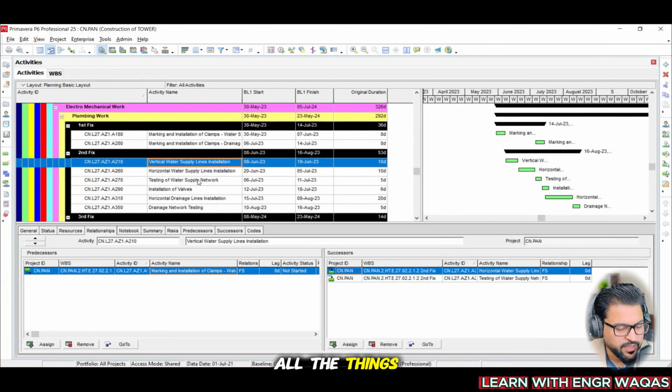Further on, we need to understand how this MEP is going to depend on what level of structural work has been achieved, and then make it relevant by interconnecting them with each other and showing their dependency. This is the big crime in scheduling: if we are not able to show the dependencies, it is a big thing which is going to delay your project. On many airport construction projects, that was the only thing which delayed them by many years, because they were not on the same page. Material was not available on site because the dependency was not clear, right?